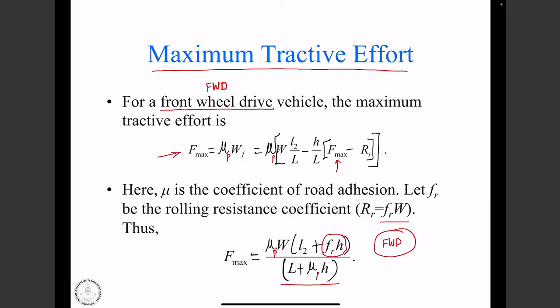On incline gradients, sir, we have considered theta to be small, but when theta is large, the rear axle will be more logical for being driven, right? Correct. When you have an incline, obviously the mg sin theta term will play a bigger role, and we need to redo this derivation, because we also took cos theta to be 1. So please redo the derivation and try it out. That's a good point.